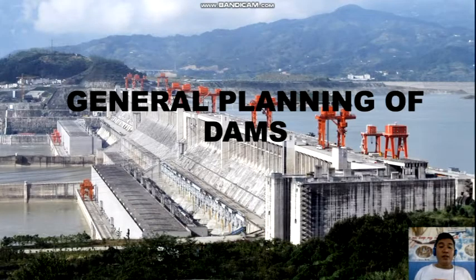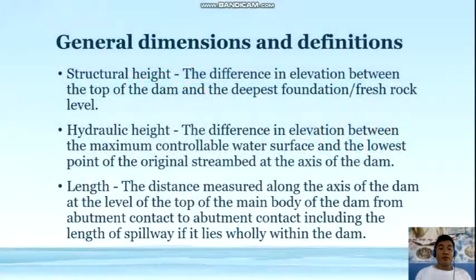So for the general planning of dams, general dimensions and definitions. Structural height, the difference in elevation between the top of the dam and the deepest foundation or fresh rock level. So next is the hydraulic height, the difference in elevation between the maximum controllable water surface and the lowest point of the original stream bed at the axis of the dam.